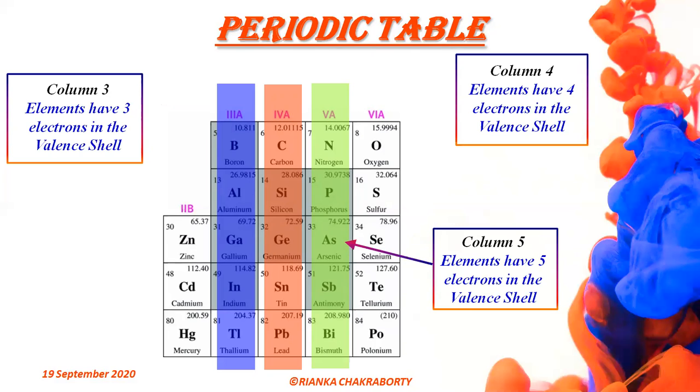The electrical conductivity of an extrinsic semiconductor is controlled by the excess free electrons or holes produced by the impurity atoms. In germanium or silicon, addition of a group 5 element like phosphorus, antimony and arsenic produces excess free electrons, whereas group 3 impurity elements like indium, boron, aluminium create excess holes.